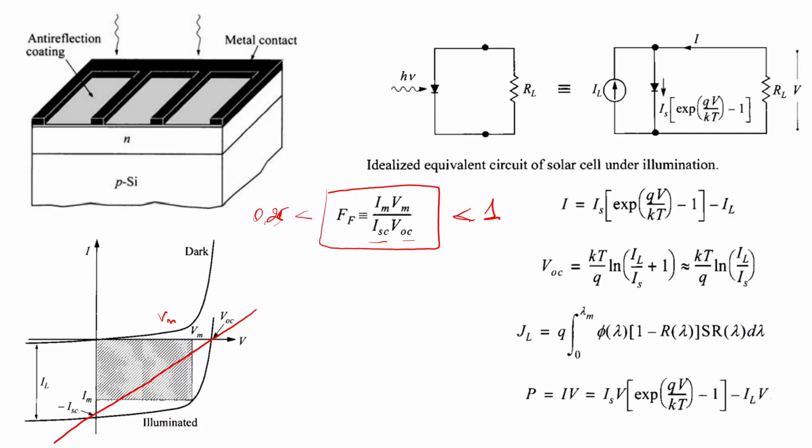In some cases it can be even worse, but then you already need to have some mess with the contacts. It could be some S-shape JV characteristic, which makes it even smaller, but that implies not only a bad solar cell itself, but also a bad PN junction and neutral regions, and also bad contacts.